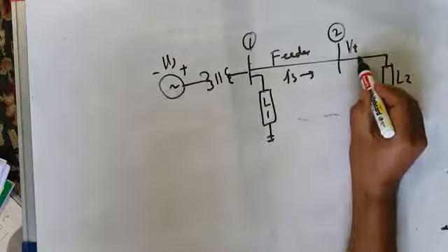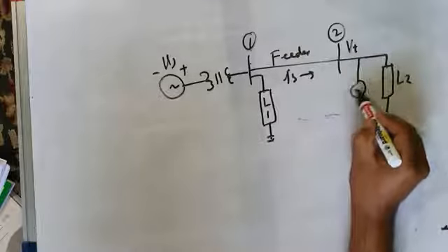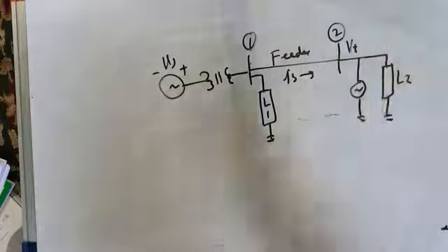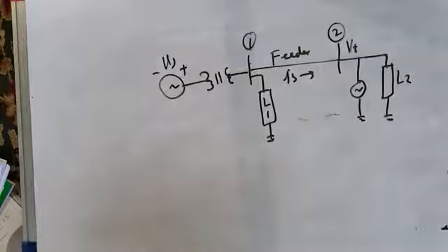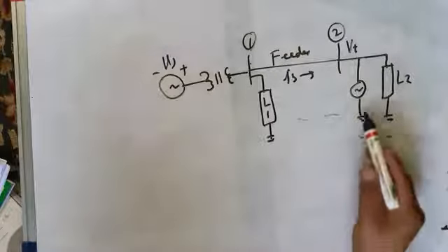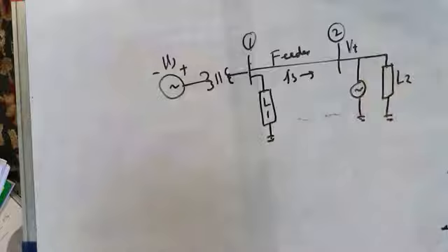So to take care of those voltage fluctuations, we have to use D-STATCOM but in voltage control mode like this, so that it maintains the voltage at the bus absolutely constant, fluctuation free. How do you use D-STATCOM in voltage control mode? We'll come to that later on when we study D-STATCOM in detail.